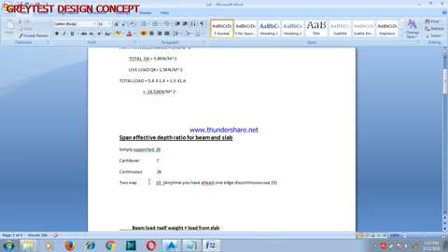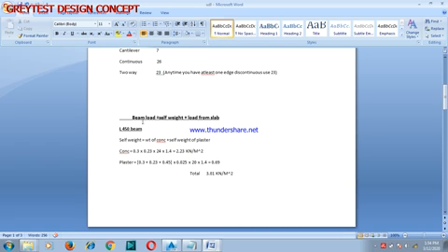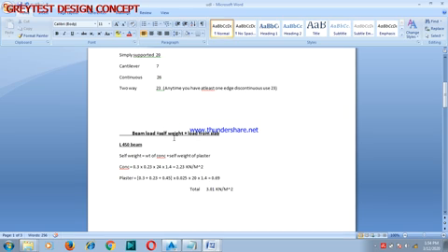Now, the span to effective depth ratio for beam and slab: for simply supported it is 20, for cantilever it is 7, for continuous it is 26. For two-way, anytime you have at least one edge that is discontinuous, you use 23. We will come back to that where you will have a better understanding. Now beam load.